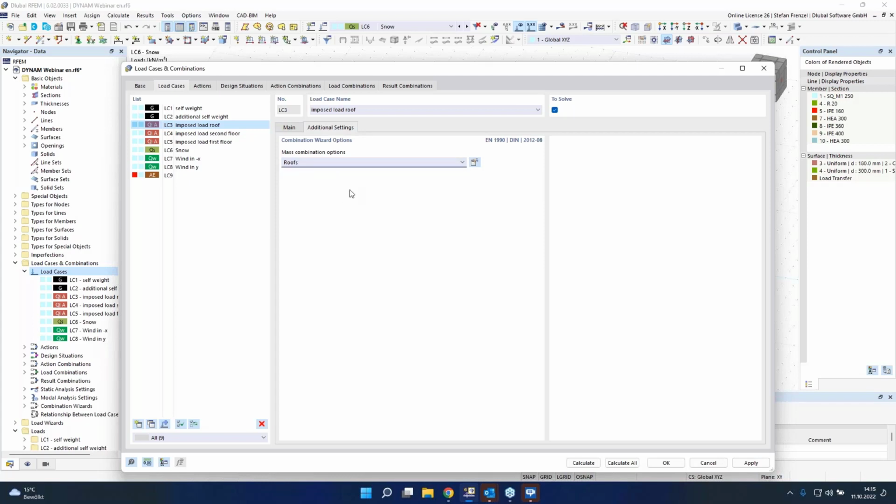And that means that the loads which you import could be smaller or could be bigger. Yeah. And here you see that we have the additional setting for our load for the roof. Of course, we say that's the roof, yeah. And the second floor and the first floor are other floors. If you use the standard Eurocode without national annex, you also have these values, and also some different values for that. So it's just in Germany that you have roofs or other floors.